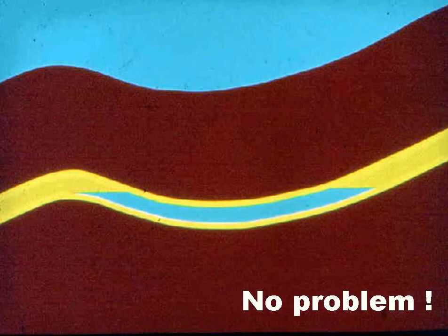This slide shows a situation which can be expected to occur during the night in a section of the sewer which normally flows under pressure flow. There is just some wastewater in that section of the sewer overnight, but that doesn't matter because there are no solids in the wastewater which will settle out because they've all been removed in the interceptor tank. So this is basically no problem. And then when people get up in the morning and start flushing toilets and using water discharging from sinks and showers, the wastewater which has been sitting in the sewer overnight will be moved down along the sewer.